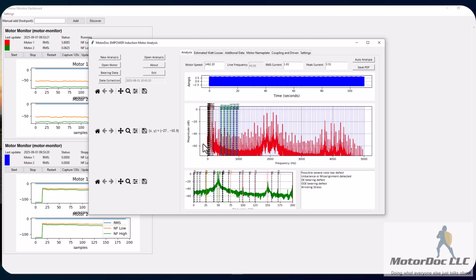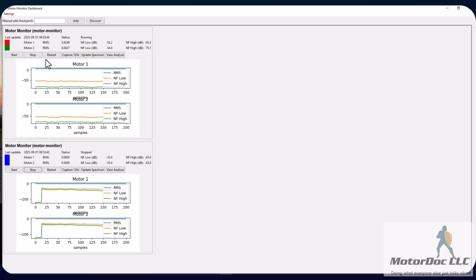So we're able to pull in the data as often as we wish, and look at it remotely to do verification. And yes, there is a casting void in that machine. It is vibrating. I do have both, and the drive's not set up properly, which is why we have these high peaks here. So that is a quick view of the system, and that is basically it. If you have any questions, let us know, and we will be more than happy to answer them.